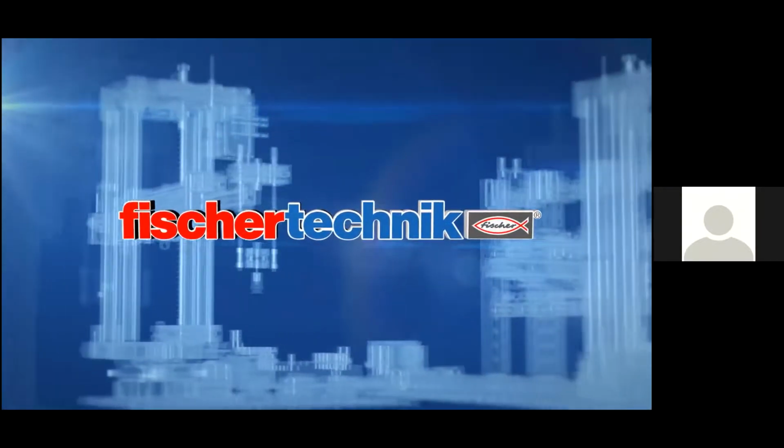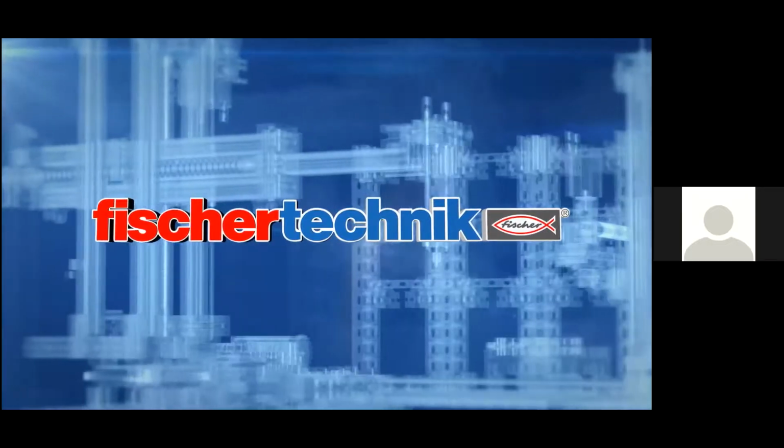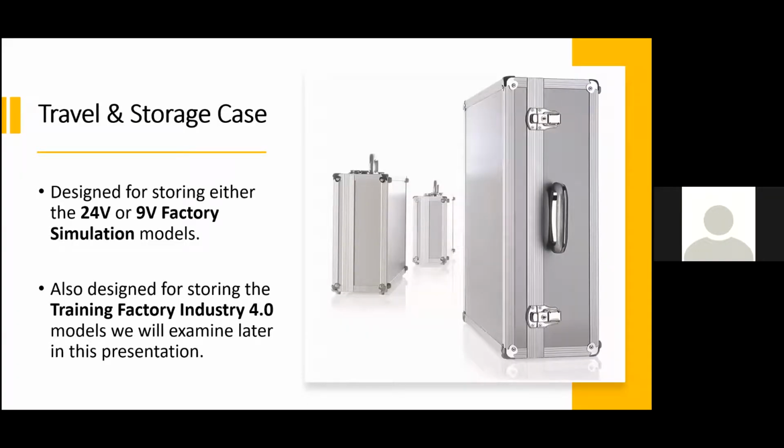Again, each station of the 24-volt version has a relay board for motor polarity reversal, and both a multi-pin connector, again 34 pins with a grid of 2.54 millimeters, as well as additional PCB terminals with push-in connections for all inputs and outputs. And before we move on to the next group of models, I do want to mention that